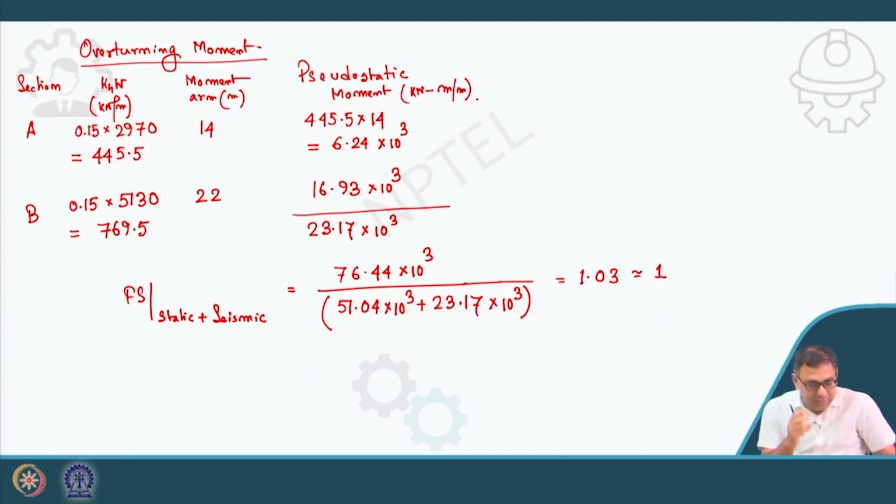Now, another thing is that pseudostatic analysis will give you the factor of safety. That means whether the slope is safe or not, under static condition or the seismic condition. You will get that idea, but it will not give us the deformation of that slope.